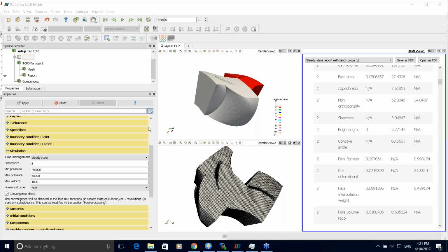So multi-stage can also be simulated here. And for high velocity or high pressure fans, compressors, there is a compressible solver, even transient, but also a transonic solver. So I believe yes, it is possible if I understand the question correctly.